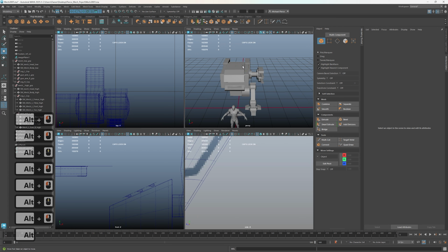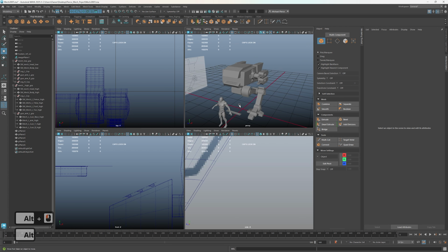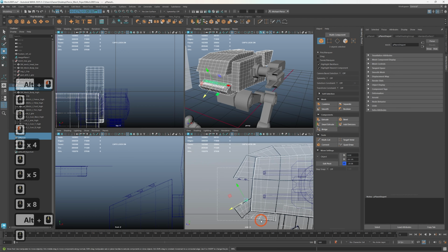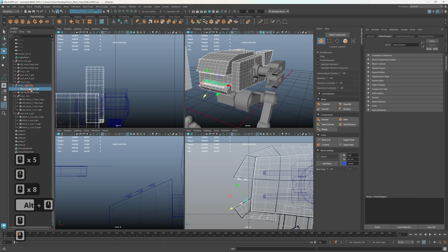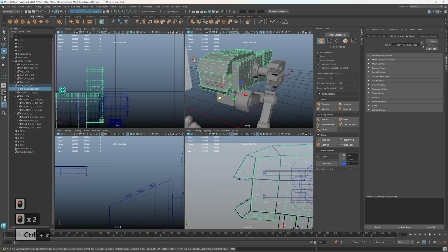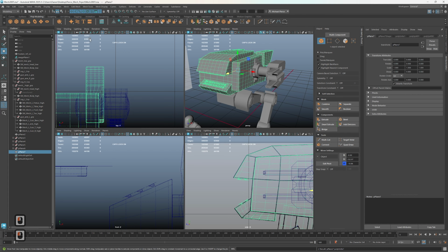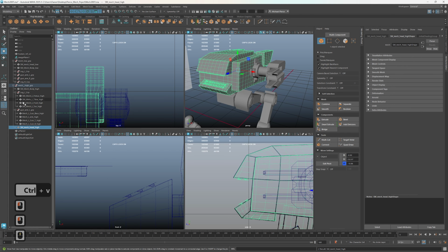You also have to be careful because you're going to need to change a few settings for ambient occlusion as well. So in my case, I'll do those details inside Substance, right? So I'm going to grab these guys, make sure I grab the head name before I do anything. I'm going to just combine these guys and delete its history. Delete history, paste, and then drag and drop that back into my high group. Make sure I put that there.